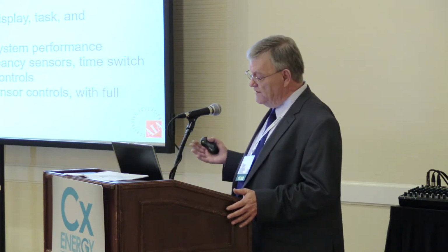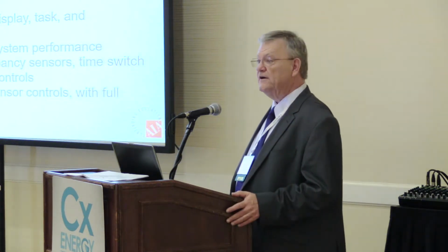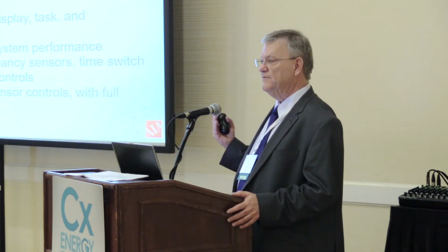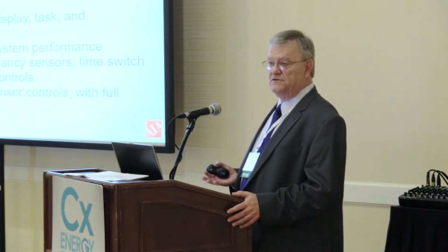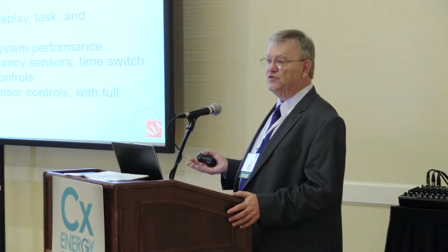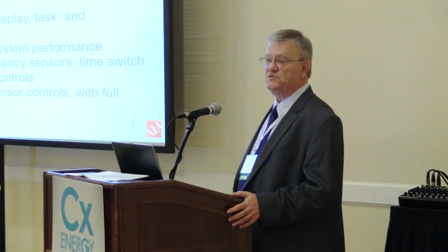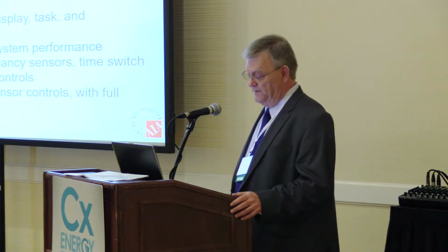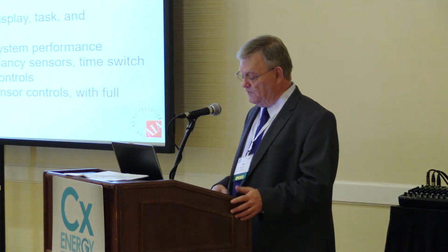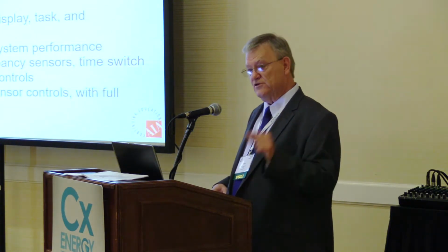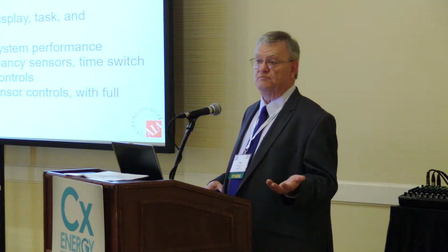That's kind of immune to interference from HVAC or by movement outside of the controlled area. I don't know about y'all, but there's an office in my building that is unoccupied. There's not a person in it right now, but the light is never off, because anytime you pass it on your way to the restroom, the sensor spots you in the hallway and turns the lights on. A vacancy sensor is immune to that, because it never turns the lights on. A person turns on the lights, the sensor turns them off after nobody moves for some period of time.